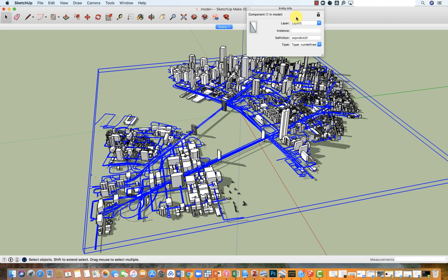We should select road layer. And you can see layer 0 is selected. Click the drop-down arrow. And right here you can see the options: cast shadows, receive shadows. So we need to uncheck both of them. Right now you can see the road shadow disappears.